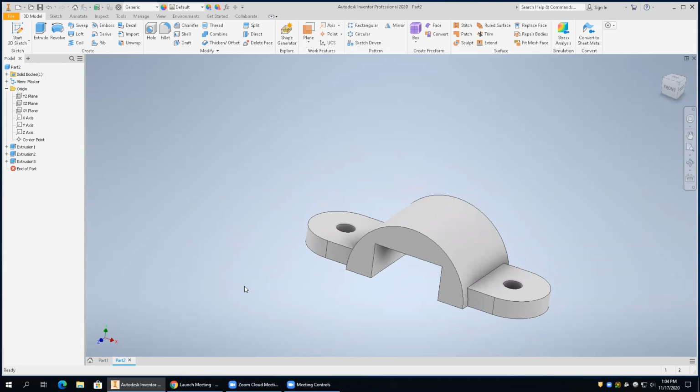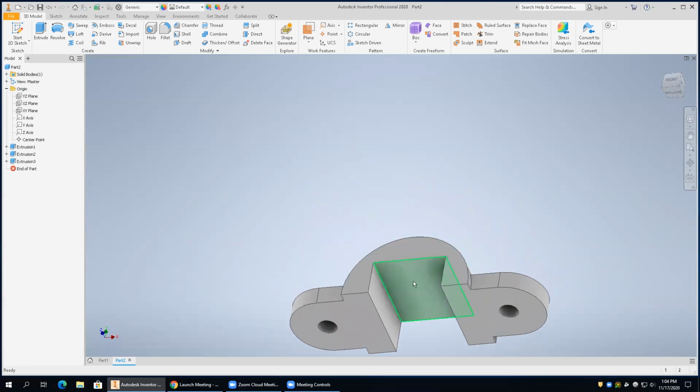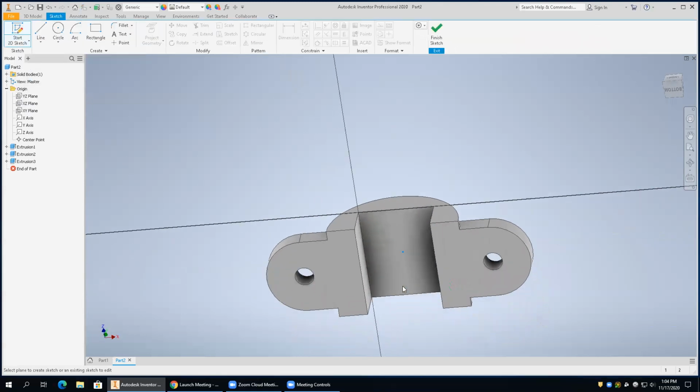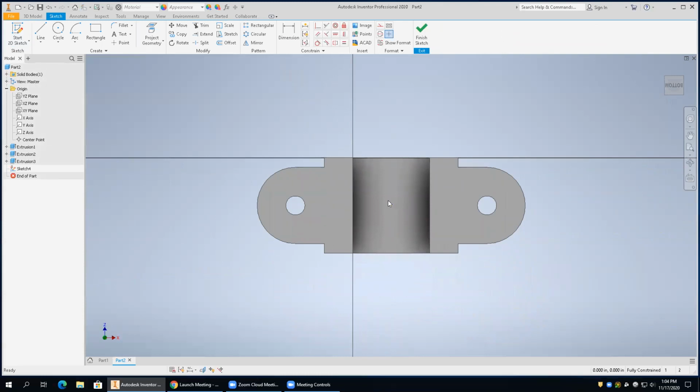All right, so we are going to do a cut feature now. We're going to have a little hole that's going to drill down through the top, and it's going to be linked to this bottom face. We're going to link it to that guy. So we're going to go into sketch mode, start your sketch, select that bottom face, and bring a circle right in the middle of that thing. Notice it shows me the centroid. Just go ahead and select it. Don't worry about its size. Just place it. When you're done, right click and hit OK.